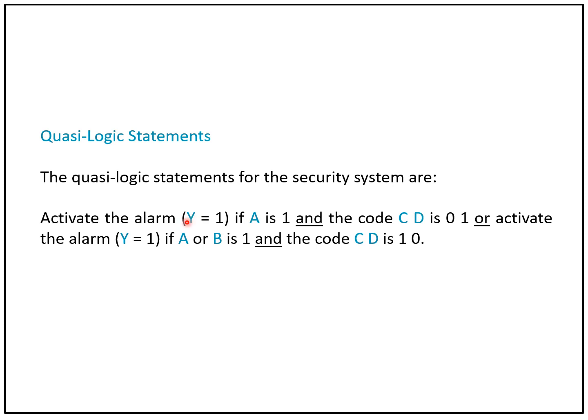In addition, because we have an OR here, the alarm will turn on also in the case where A or B, which means one of the doors or windows is open, or there was a motion detected in the house, when the user has selected active state number 2, which corresponds to the case where the occupants are outside the house.